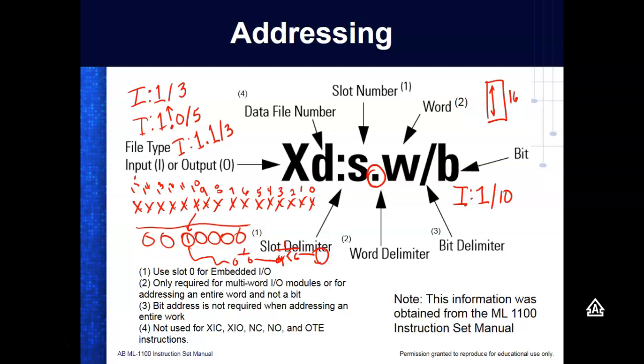And then we store the zeros into an output file. And then when the PLC scans the things, it just copies those into the actual true output. So a 1 would probably turn an output on, and a 0 would probably turn an output off. Of course, it depends on how you wire it. So that makes sense. So every terminal is assigned a bit address.